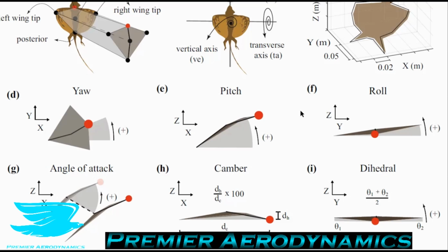What this does is it means that the wing on the other side, which is flatter, is actually producing more lift and a greater moment about the axis of roll. And then that restores the wing platform back to a more symmetrical geometry. That's how dihedral works. So that's very stable. There's another way that dihedral works to make the wing more stable as well, and that's effectively called the pendulum effect. So you have the center of mass usually below the wings themselves. So it's just effectively like a pendulum where the mass naturally wants to rock back into a stable position.